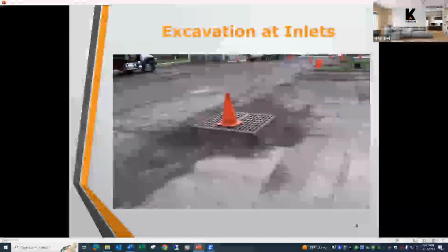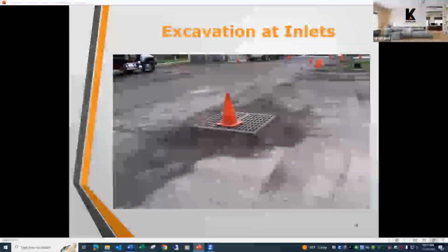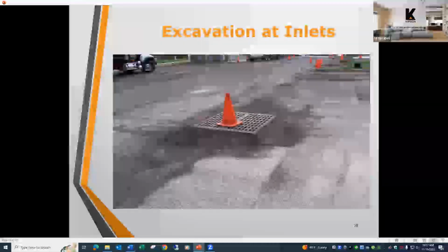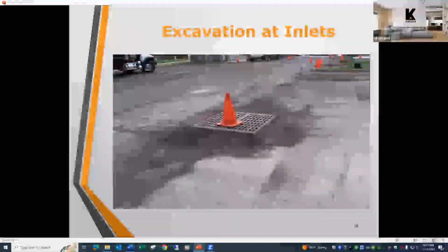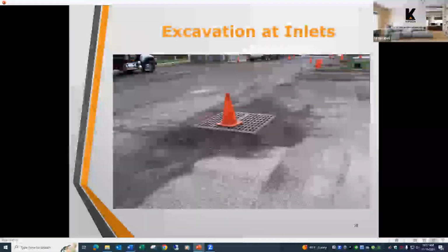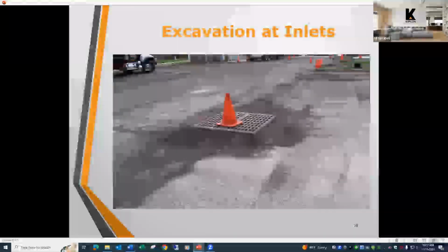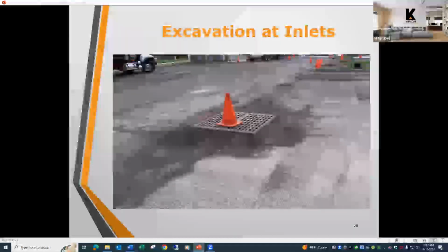And then after the pavement surface is milled, it's going to look like this. It's going to have some striations in it. Usually you can drive on the milled course. So usually the contractor will come through on day one and do the milling. The community can put vehicles on it again. They can park vehicles on it. They can drive over the milled surface typically that evening.